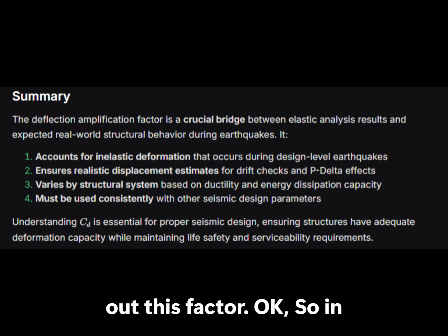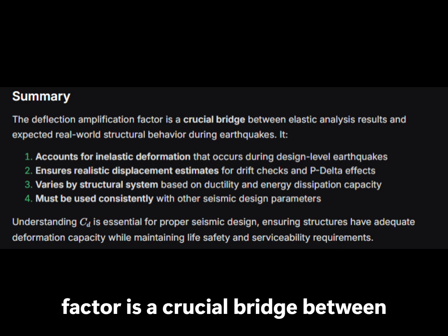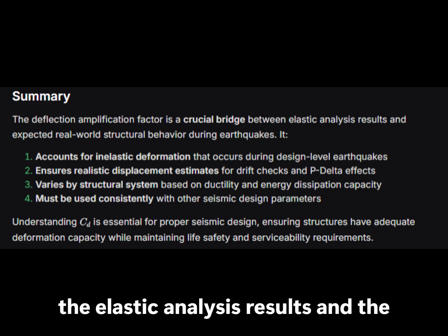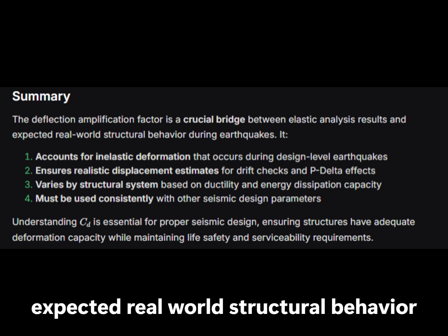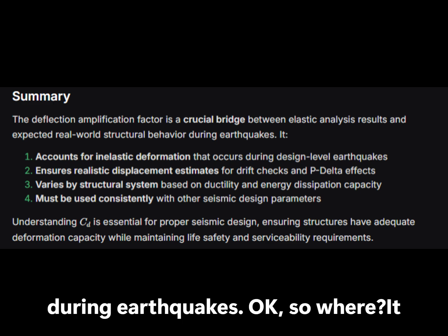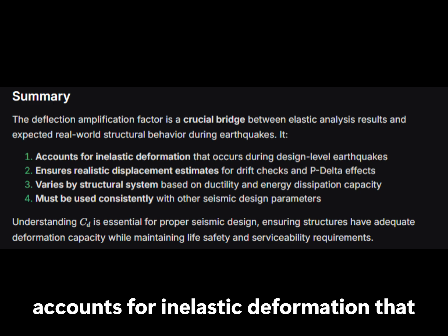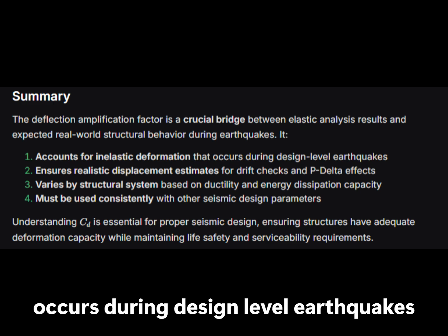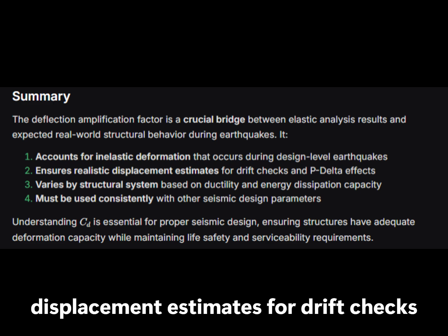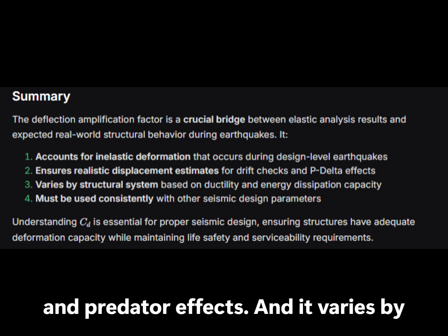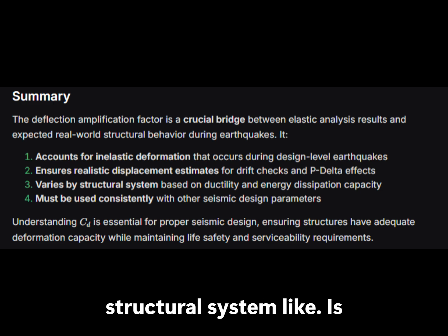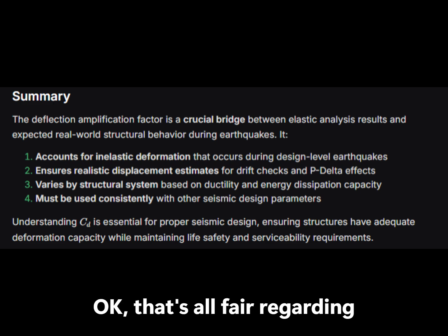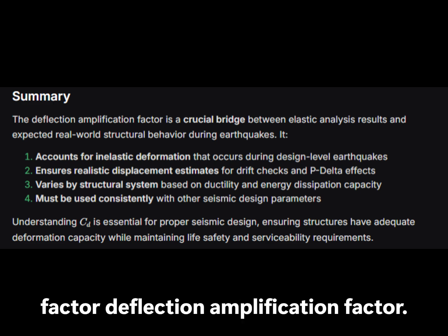So in summary, the deflection amplification factor is a crucial bridge between the elastic analysis results and the expected real-world structural behavior during earthquakes. It accounts for inelastic deformation that occurs during design level earthquakes, it ensures realistic displacement estimates for drift checks and P delta effects, and it varies by structural system, based on whether it is RCC, steel, wood, or masonry. That's all regarding this factor, the deflection amplification factor. Thank you.